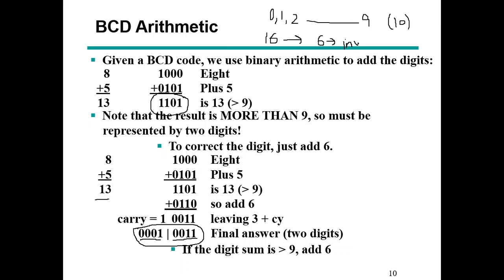मैंने शायद उस वक्त भी आपको कहा था कि ये 6 का नंबर आप याद रखें. ये 6 का जो नंबर है इसको आप याद रखें. वो यहाँ पे हमारे काम आएगा. सो 6 कोड्स आर इनवैलिड. हमारे पास जो कोड्स हैं वो 0000 से स्टार्ट होते हैं. BCD 8421 कोड 0000 से स्टार्ट होता है. इट रिप्रेजेंट्स द डेसिमल 0. और ये कोड्स फिर जाते हैं 1001 तक. दिस इज डेसिमल 9. सो दीज आर वैलिड BCD कोड्स.